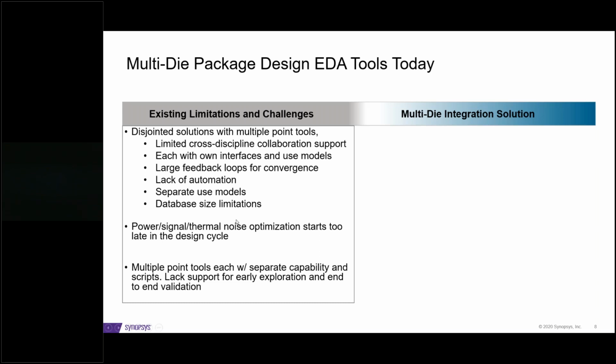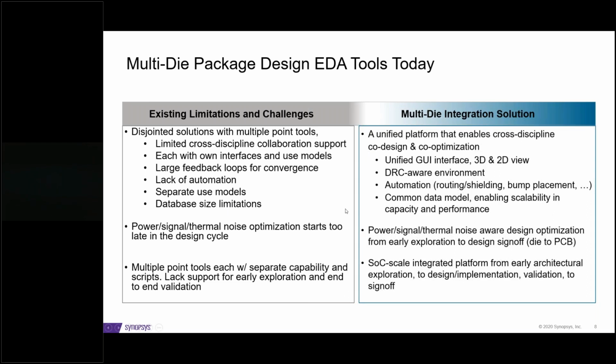So in order to be able to provide an environment, ideally, a unified environment that you can do all your explorations, planning, designing, analysis, all in the same environment, that minimizes a lot of movement from one tool to another tool. And also by bringing in a lot of automation, bringing an environment that is DRC aware, it's aware of the rules, that when you're making wire connection, you know already you're making a mistake, so you don't make it, or especially when it's automated, it would just follow the rules that you are feeding it. It would be ideal. It would minimize the number of iterations and your design cycles.